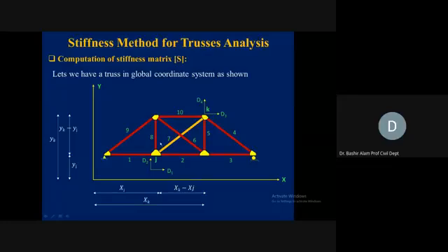Vertical projection, if we see, so the vertical projection again from the origin, these distances are given. You see the yj up to here, and you see yk, which is up to here. So the vertical projection from here to here, this is the vertical projection of this member 7, which is yk minus yj now. We can apply now a trigonometric function to put this theta in terms of these coordinates.